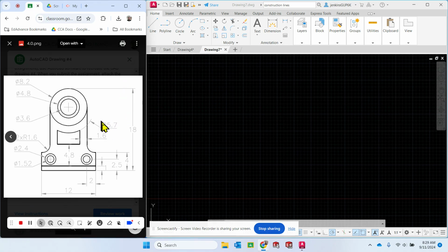Second, I'm noticing that there's a bunch of circles here. If that's the center point, because that crosshairs is the center point symbol, I have 1, 2, 3, and kind of 4 circles all around that center point. Now, I know we're just getting used to looking at dimensions, and so there's a lot of dimensions on this page, but one of the dimensions it doesn't tell us is where exactly that center point is. I know it's in the middle, right? But it doesn't say how high up from the bottom or anything else it is.